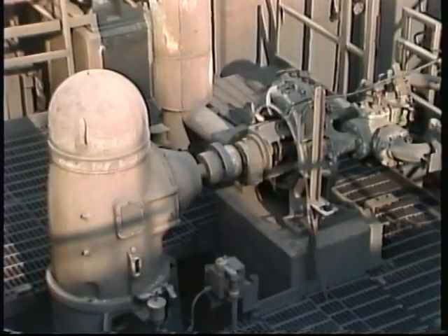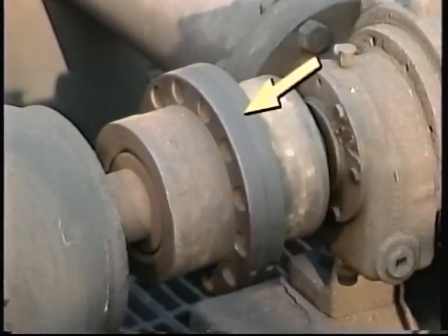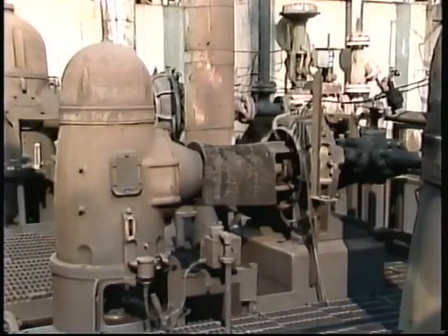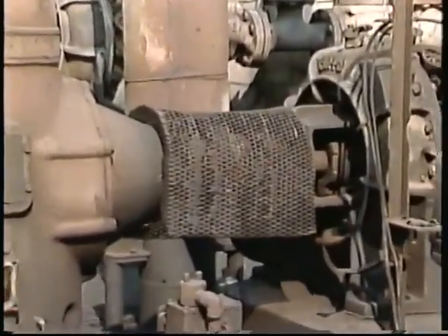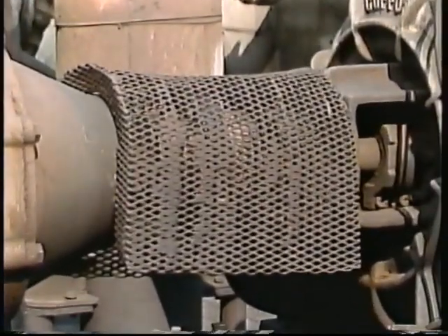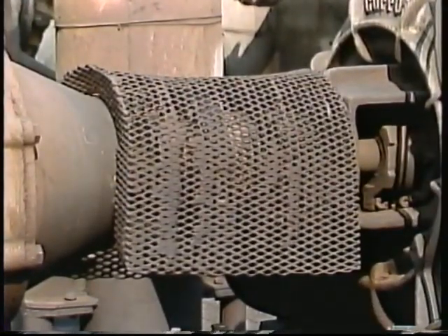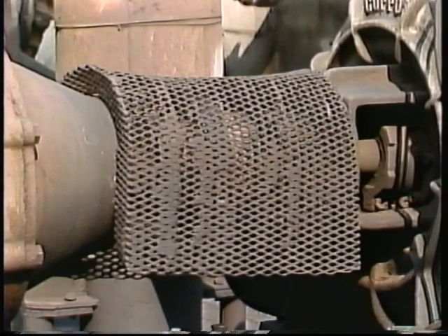In order to put the rotor's mechanical energy to work, the turbine's power must be transmitted to a piece of rotary equipment. A coupling is used to connect the turbine to the driven equipment. For safe operation when the turbine and its driven equipment are running, the coupling should be covered. The coupling cover, or guard, prevents personnel from getting their clothes or fingers caught in the rotating parts.